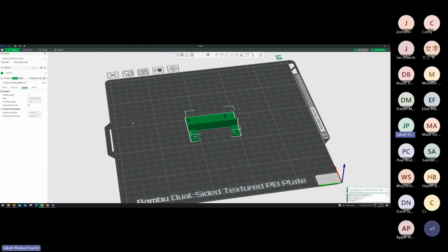And if you are printing in ABS, it is also good to have support on the bed, so it's not popping up from the actual printing. I had that kind of issue many times with ABS, and after a couple hours of printing, I was looking at, okay, what's going on, and I just wasted time. So it's good to play around in advance with the specific settings.